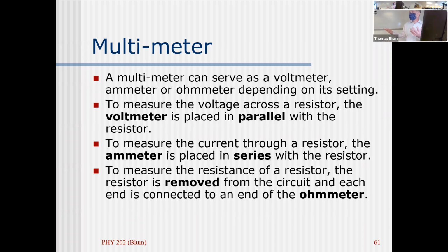They share current. So you're changing the current a little bit, but the point with a voltmeter is you try to change the current as little as possible. So you try to get just a teeny bit of current to go through the voltmeter. So you give it a big resistance. If you bring out a voltmeter, you'll see that it has a little resistance reading on there, and it's usually quite large, like mega ohms.